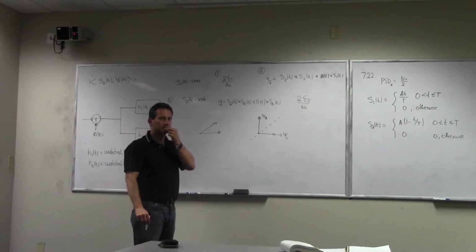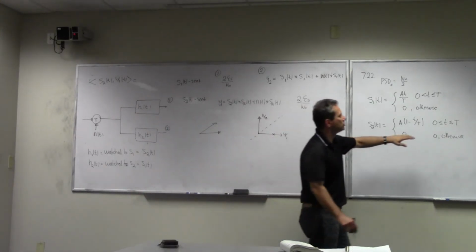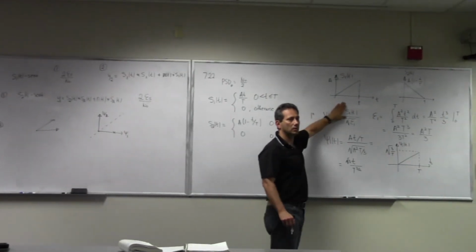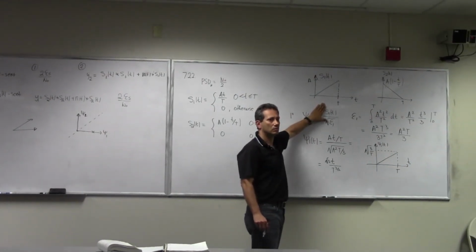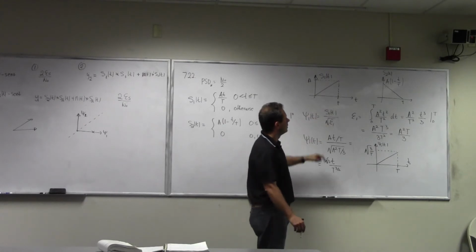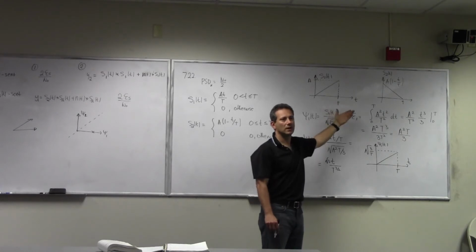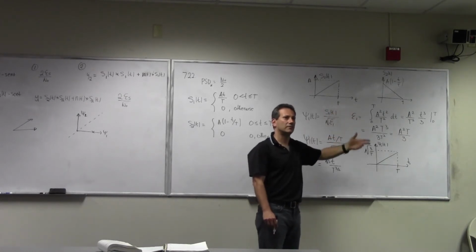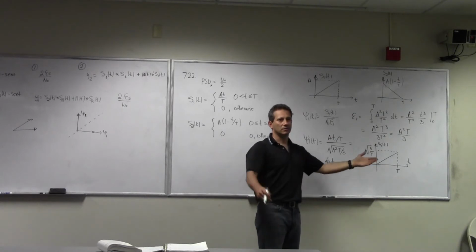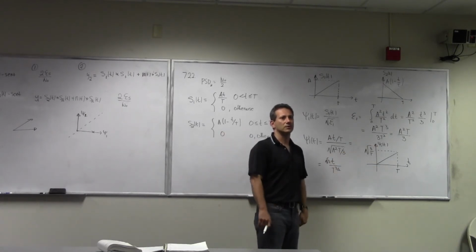Go ahead. Well, this is actually a basic question. In the beginning you said that the signals are not orthogonal, so where can we see that? The dot product of these two is not equal to 0. Do you see that? Some component. For starters, both of them have DC values. When you have two signals that have DC values, the product will have a DC value. And then the integral over something that has a DC value has to be different than 0.